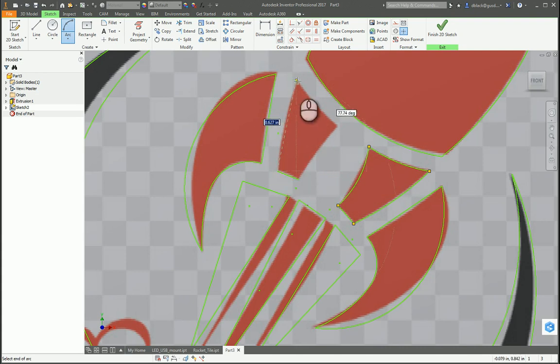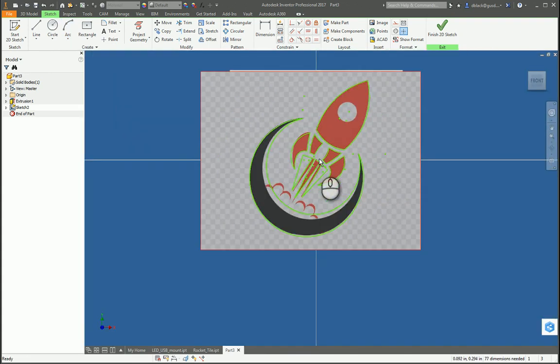That gets a lot easier to program the toolpaths for, to machine on the CNC router. The detail stuff gets really tricky, and we'll have to go to a smaller diameter tool to get in there. So I recommend keep it bigger. Remember, an 1/8 inch tool cannot machine anything smaller than an 1/8 inch.